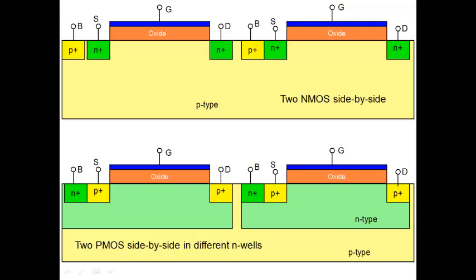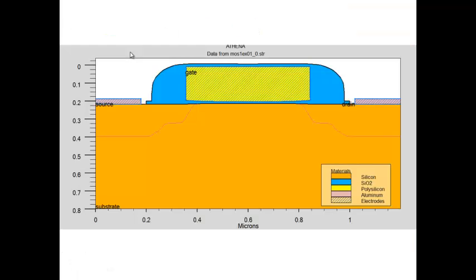Dimension. So this is a rather simplified schematic of the MOS transistor here. This is a more accurate picture. You can see here a more accurate picture of the MOS transistor. So this is your gate here, which is polysilicon. This is your oxide, and there's a thin oxide here. Polysilicon is heavily doped and it acts like a conductor.